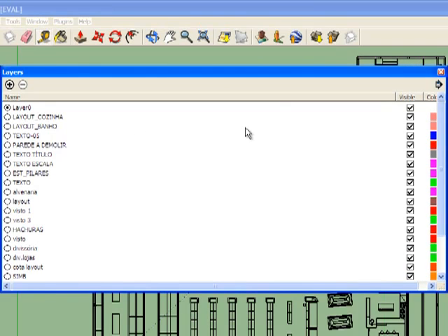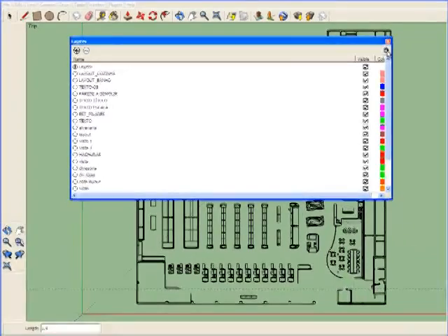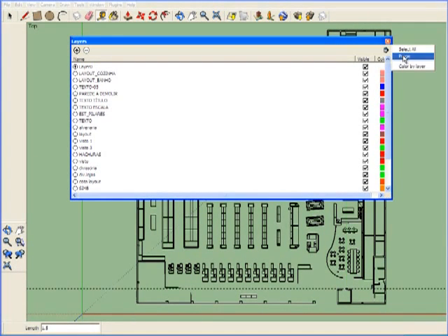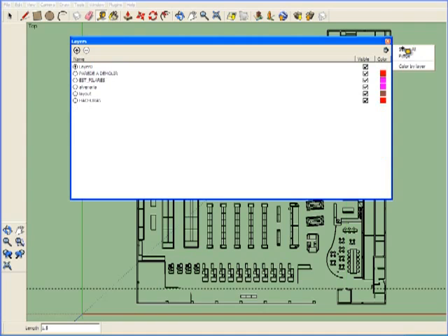It lists the layers, their names, and their colors. Then you have this little arrow here you can click, and it gives you an option called Purge. When you click this, it is going to get rid of all the layers that are unnecessary and that cannot be seen. I suggest using this. It'll greatly minimize your file and the amount of time it takes to convert the file.